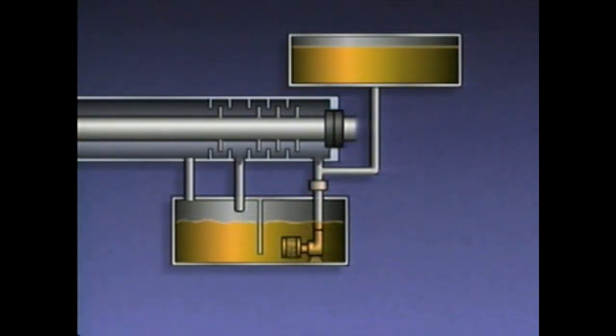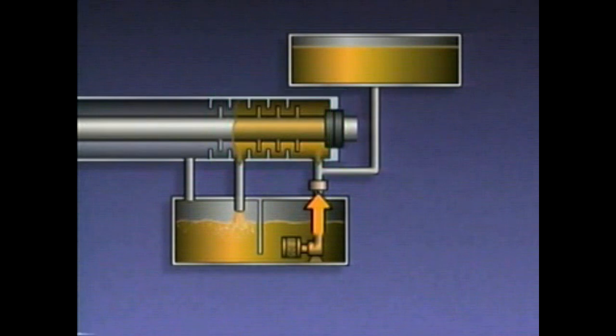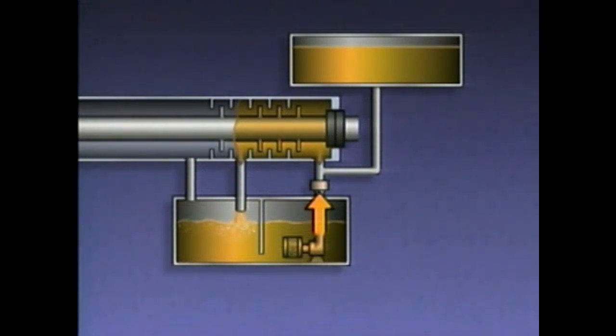During operation, the oil is pumped through an oil supply line and into this space around the shaft. The mechanical seal prevents the oil from leaking out of the compressor. The oil flows through the labyrinth seal and prevents gas from leaking out of the compressor along the shaft. The oil flows through the seal because the pressure of the oil is greater than the pressure of the gas in the compressor. The oil then flows back to the reservoir through an oil return line.